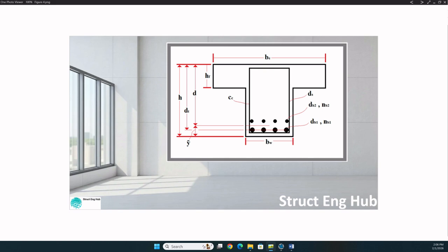A flanged beam has a flange and a web, where the flange is usually part of the slab system and the web is the drop of the beam below the slab. If the beam under consideration is intermediate and has slabs running on both sides and is cast monolithically with the slab, the beam will have a T-shaped cross-section.